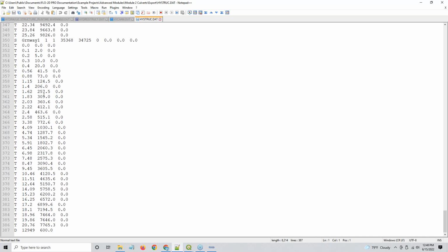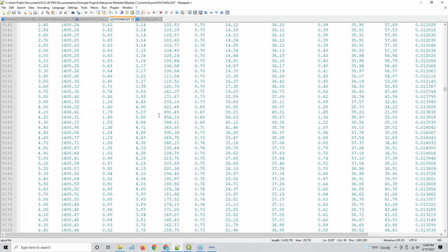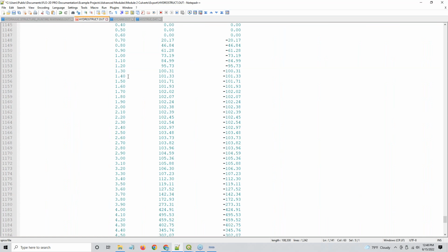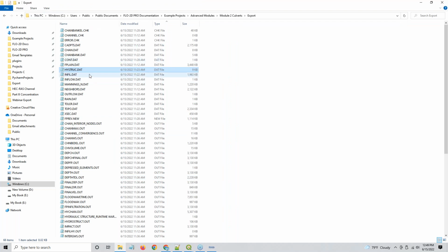So you can follow this and you can see that we had about 500 CFS. So we were around 2 feet of depth in our channel. And then you can just do comparisons, slightly upstream or slightly downstream, and make sure that those are in agreement, and check it here as well, and just compare them if you have a structure that you're worried about. Also, another thing you can do on those channel ones is, let me grab something real quick.